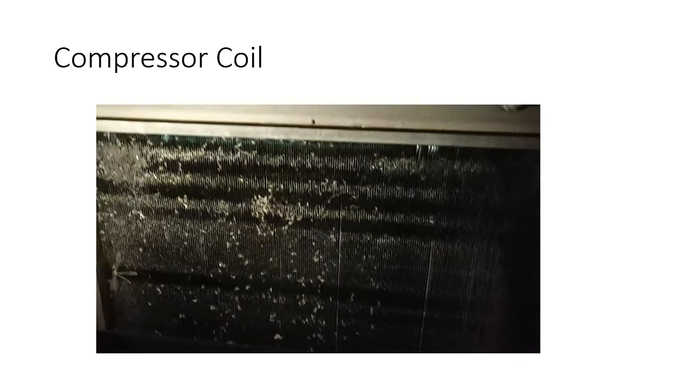In this picture we can see the compressor coil. The compressor coil is blocked with dust particles in many places, and because of this choking, the cooling efficiency of the compressor is drastically reduced. It is recommended to clean the compressor coil with soft and smooth brushes and to remove this choking dust to have better cooling efficiency.